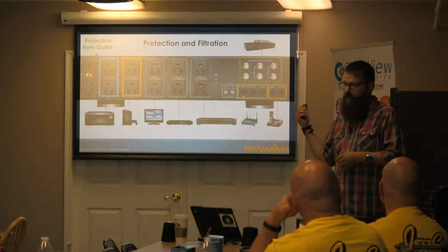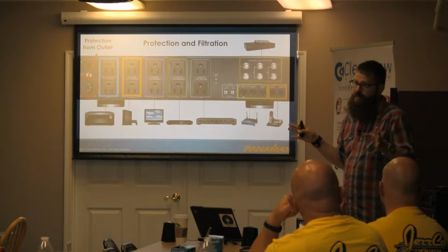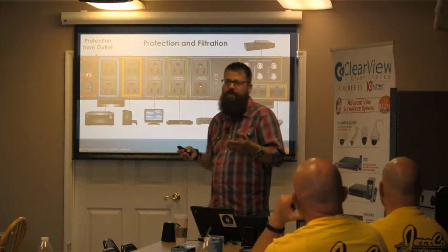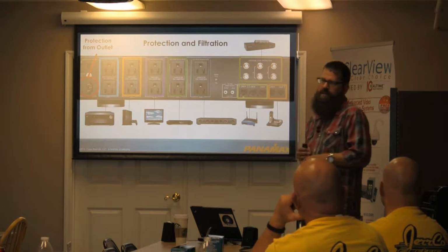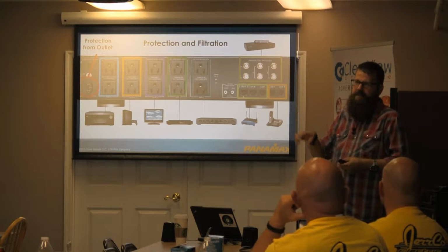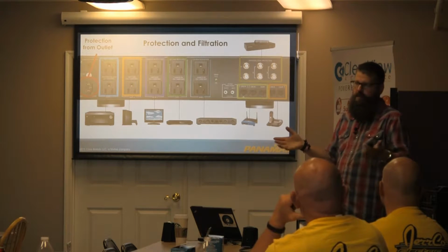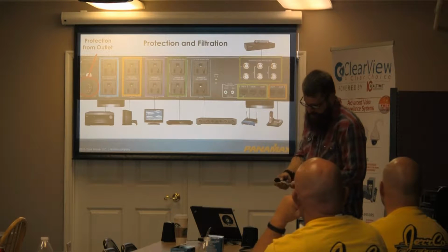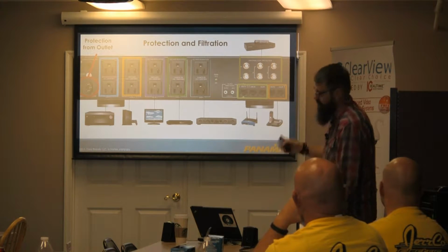Sure enough, when I put a Panamax piece in, it didn't do that. I wanted to see if this really is doing what it's supposed to be doing. My dad didn't care, he's old school. It's like, every time I hit it, the lines go across, but I can still understand what's going on. So we plugged that in, and that solved the problem with the isolation there, so it wasn't cross-talking.